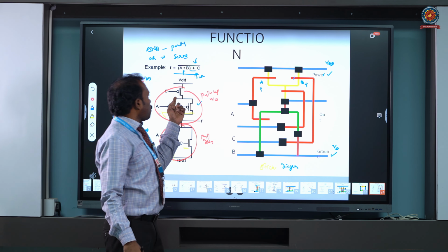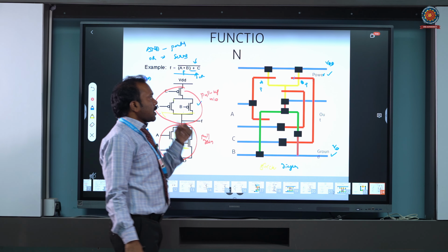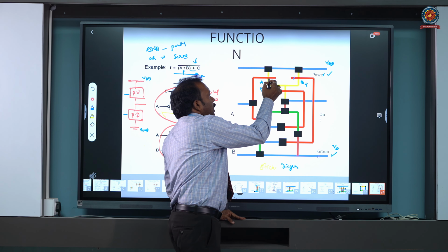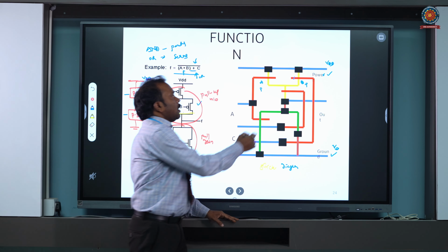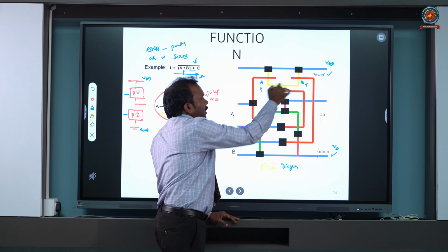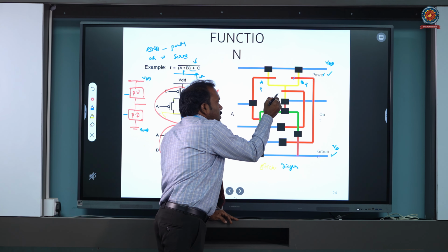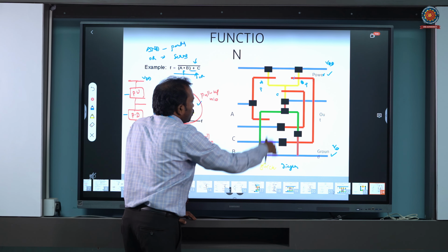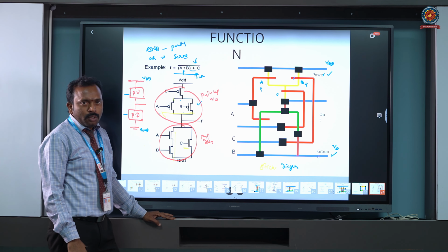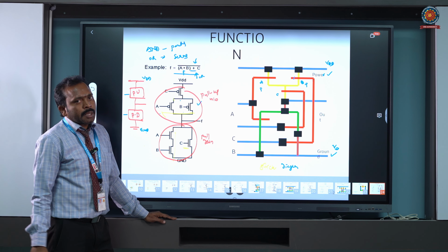And one more, we have a PMOS transistor, that is the C transistor, red over diffusion again. And these two, the parallel combination of A and B, are connected to C. Now here the C is connected, over which the red is drawn, and this forms your transistor C. And similarly, this is the connection that we used here. The dark brown can be used, or the blue can be used as a metal.